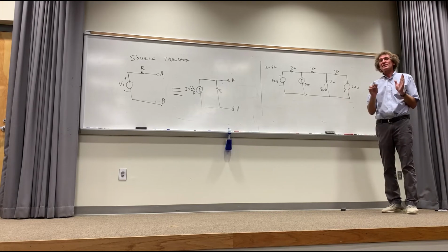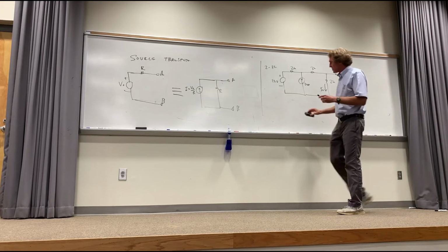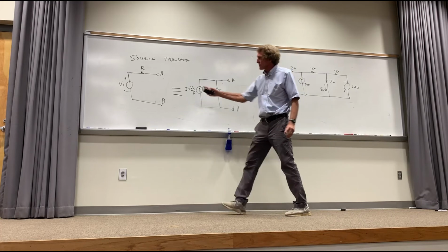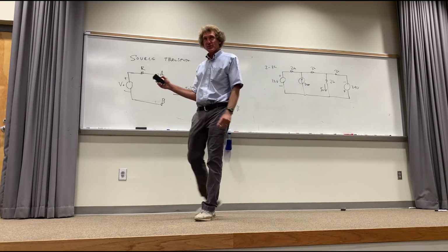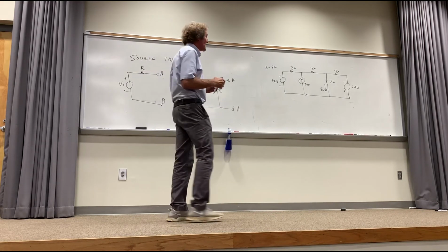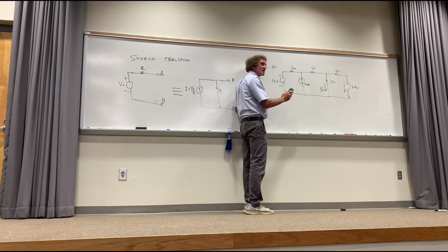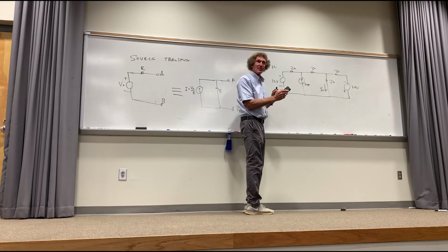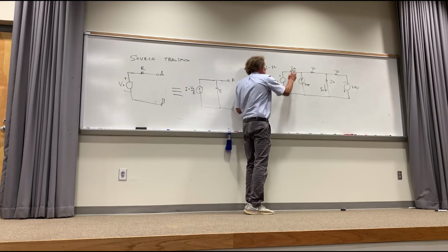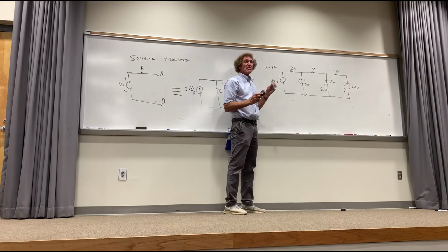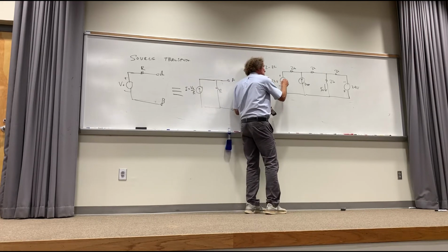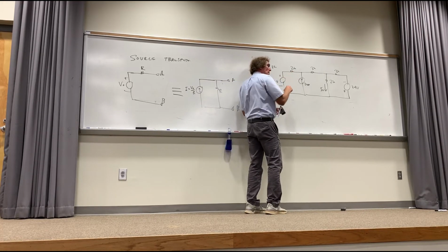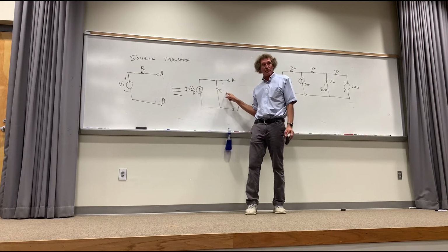Now, I want you to listen to what I'm saying, and hopefully you'll appreciate it. You see how these two are identical, right? The whole idea is you do these transforms and then absorb an element. Now, listen to me, because this is how you add current sources in parallel also: these two could be replaced by a current source in parallel with that 2K. How many see that right there? You all see it in the back? Can you point it out one more time? This and this could be replaced by a current source in parallel with 2K, based on this, right?